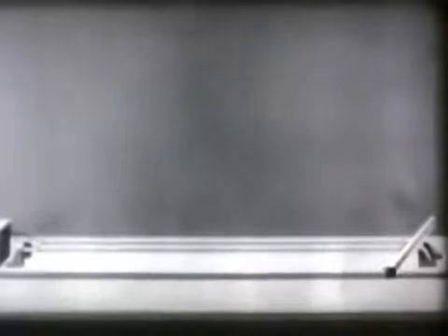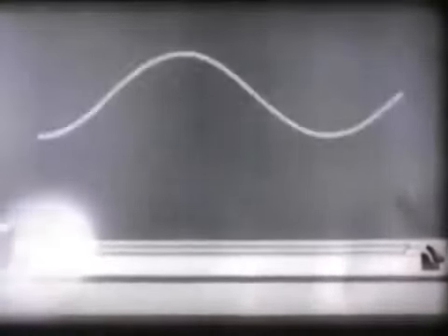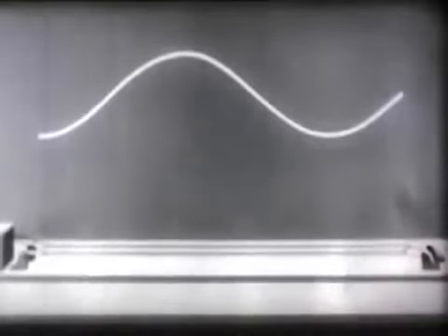Now here's another phenomena of resonant transmission lines. When an ordinary fluorescent lamp is placed near the line, it can be used as a voltage indicator. When the tube glows the brightest, it indicates a point of peak voltage in the line. A voltage plot of this line would look like this.